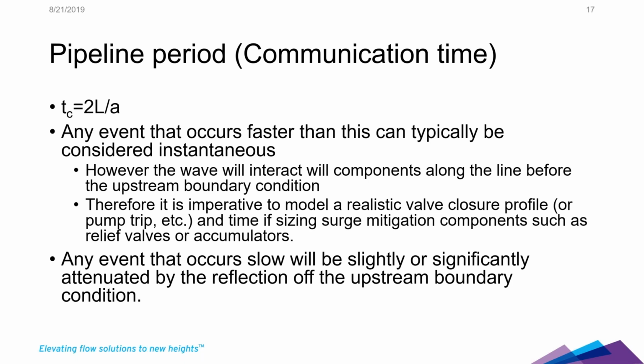And that means it's kind of imperative to model a realistic valve closure profile or a pump trip if sizing surge mitigation components, such as relief valves or accumulators. If you have a really long line and a sudden valve closure, say like you're doing a loading arm case, you have an emergency release coupling, getting that valve closure profile and that time accurate is going to change how your relief valve responds.